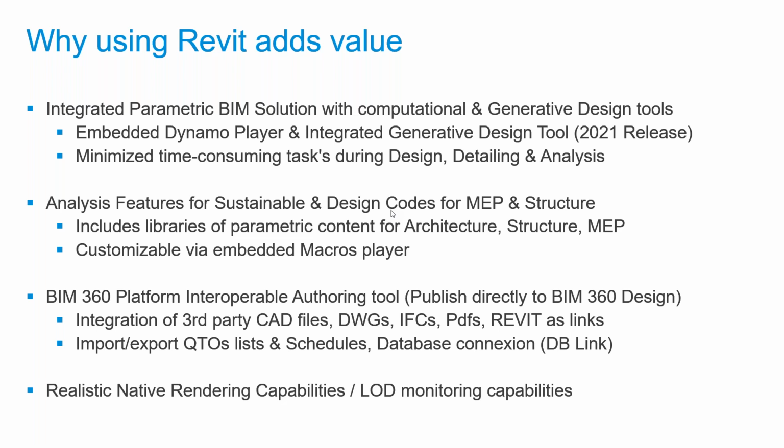Anything else you want to add there, Nabil, as far as the back and forth between the two? Yeah. So in a traditional way of working, the export to AutoCAD feature is used to bring your 3D plant model into Revit. However, nowadays, when you have a BIM manager assigned to a project who is in charge of aggregating all the models from different disciplines, we tend to see more Navisworks as the desktop product to aggregate that data.